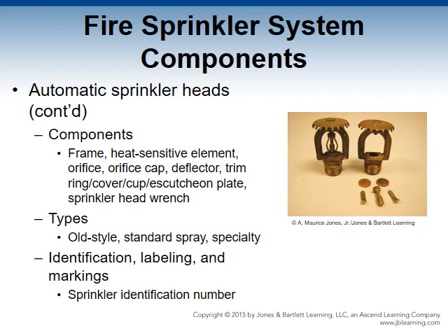A sprinkler head wrench is a tool designed to install or remove a sprinkler head. Looking at our types of sprinkler heads, you have an old style head, also known as a conventional head, which was the majority of the heads until the 1950s. It could be oriented to discharge water up and down, with 40 to 60% of the water initially flowing downward upon activation.